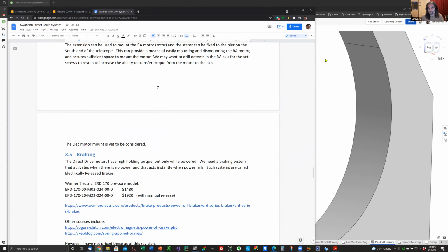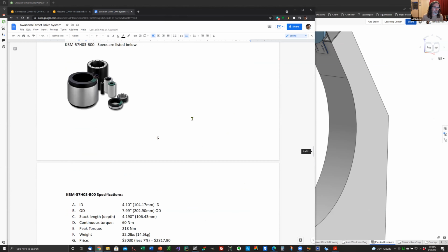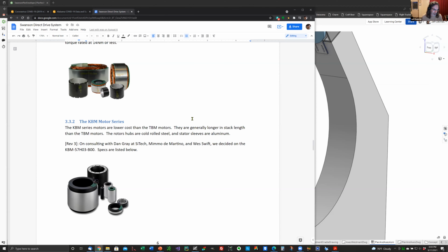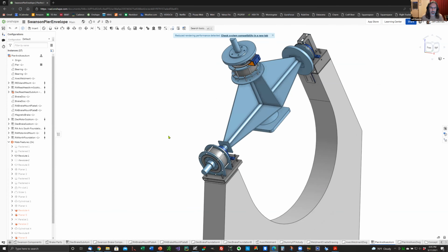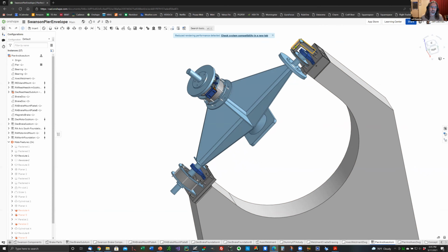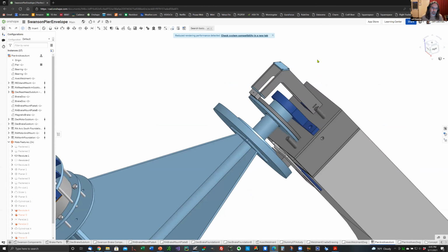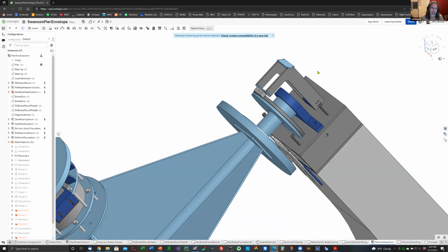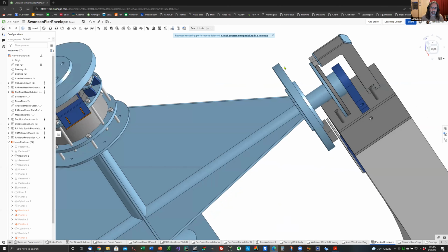So at this point, we also had to have quite a few parts manufactured, like all of the motor mounts. The motors are called frameless motors because they don't come with any kind of mounting frame. So we had to design and manufacture the frames, and we got manufacturing donated primarily by Teledyne Brown, but also by DSC Technologies up in Tennessee through Lonnie Puderbaugh. He knew those guys. But all of these metal components are used to mount the encoder rings. So the rings are truly rings. You can see they're just rings. So we had to mount them on a disc and then mount the disc to a hub, and connect the hub to the axis.